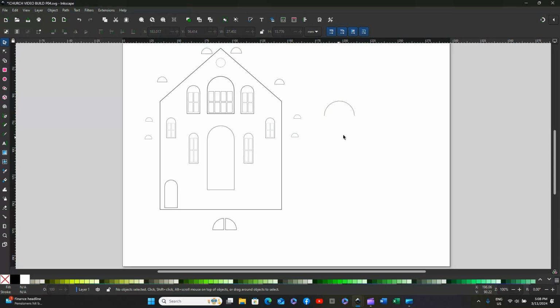Unfortunately, that's an open arc. So what we have to do then is just click on that arc on the circle tool, and then you will see that you can change it to a closed arc, which is here. So just click that and it closes the arc. This part here catches out so many people when they don't see it illuminate.